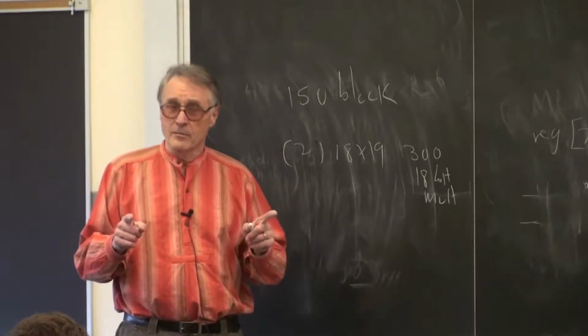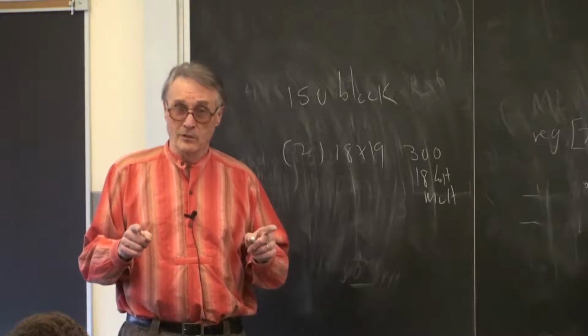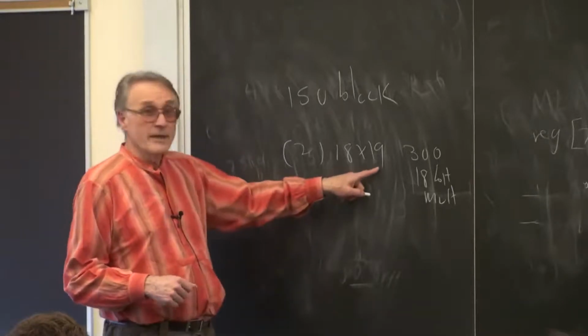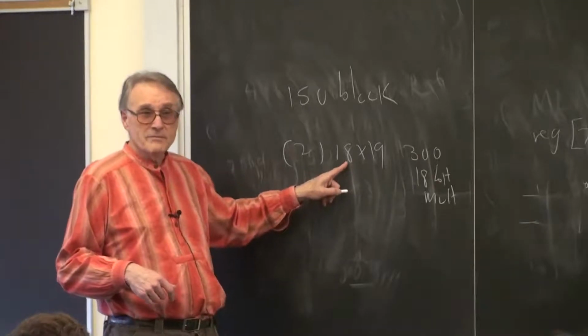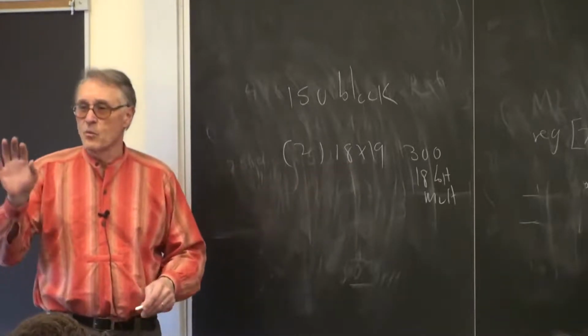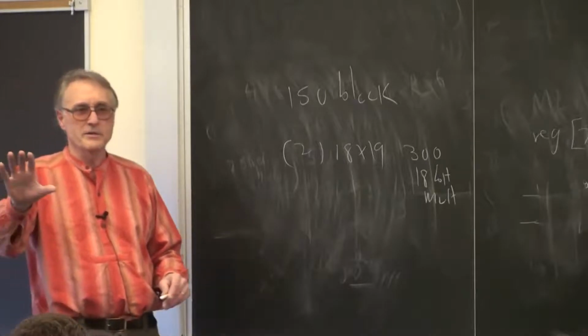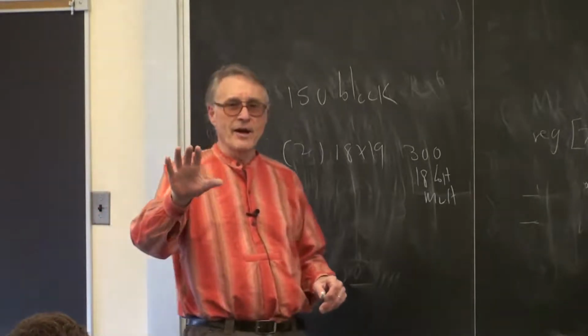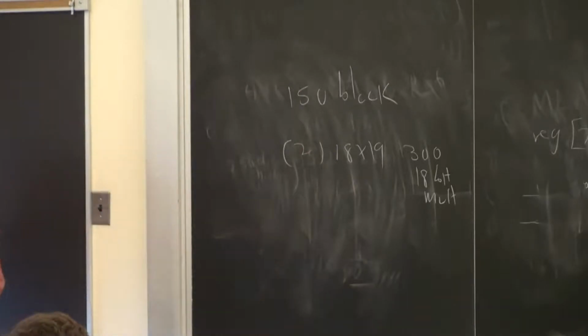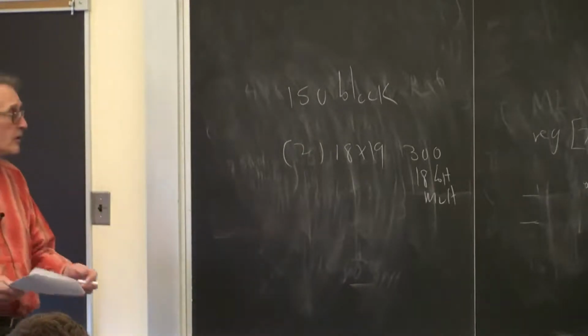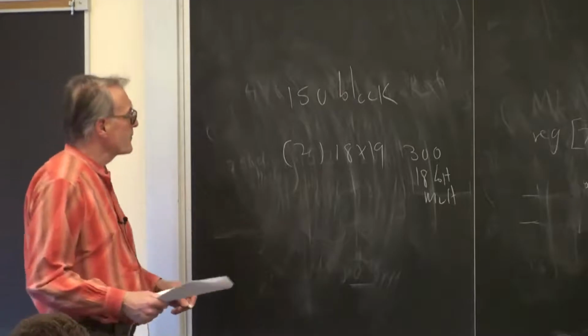So if you add them before you do the multiply, you get 19 bits. And then the coefficient is 18 bits. And so this halves the number of multipliers that are necessary for implementing FIR filters. That's cute. Not necessary to know for this particular lab, but cute.